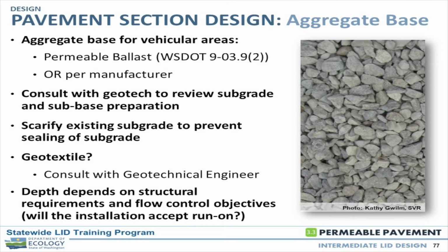Now, we talked about, with Matt, reviewing our subgrade and understanding the characteristics of our subgrade. Preparing the subgrade is a critical design factor, and one that's somewhat unique to permeable pavement, and probably an area where the industry needs more learning and advancement of understanding. Typically, if we're going to do a traditional pavement, we want 95% compaction, but 98% is better, and if we wash out a few concrete trucks in there and just harden up that surface, that is generally our approach. But that is not the approach at all that we want to take with permeable pavement, of course.